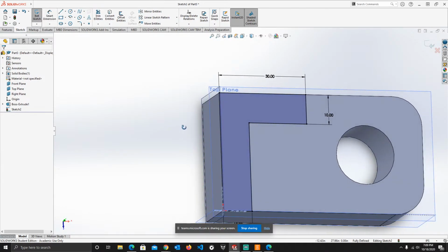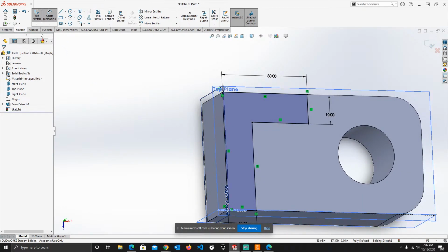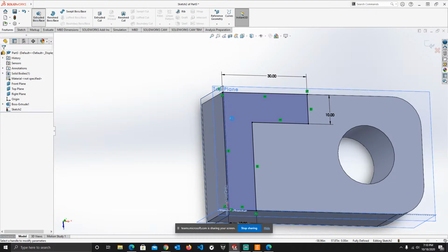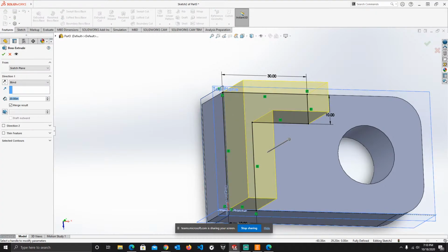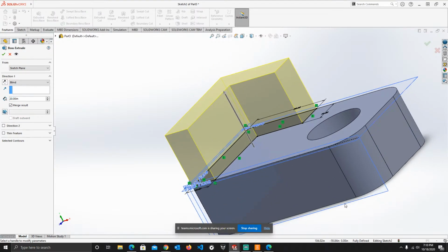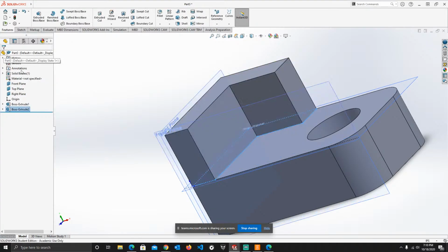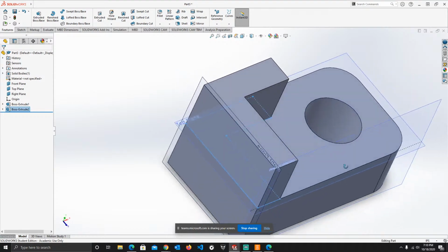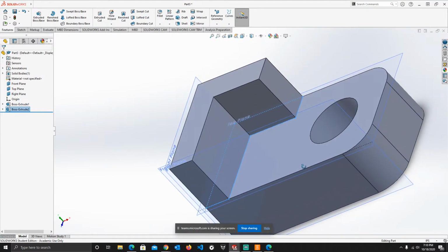Our drawing is perfect. So let's go ahead and do an extrusion. Features, extruded boss base. We're going to go up now by, let's see here. If we made this 20 inches in height and your overall height is 40, then that means that this extrusion should also be 20 inches in height. I'm gonna press OK. Done. We have a nice L in there. Sweet.